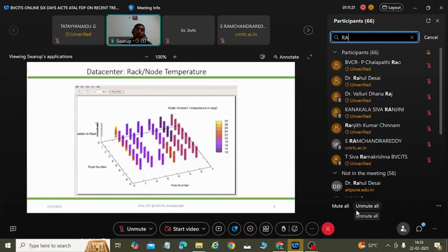That is the speed at which the air is thrown from the bottom. Now what happens? Each server has front-end fans which suck the cold air inside, and then the hot air is discharged from the back. In this mechanism, if we increase the CFM, the velocity of this cold air increases, and the fans are not able to suck it at that particular speed.